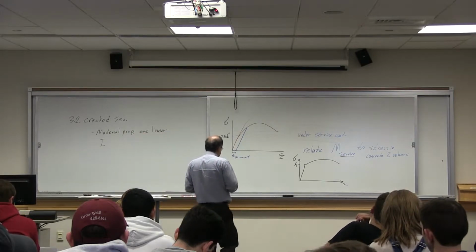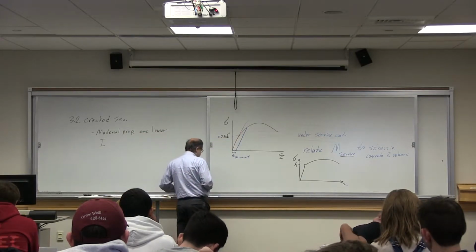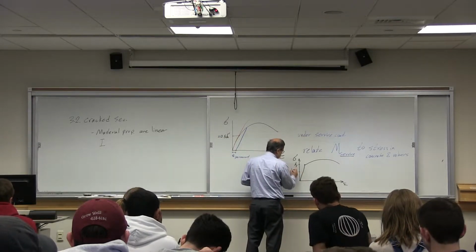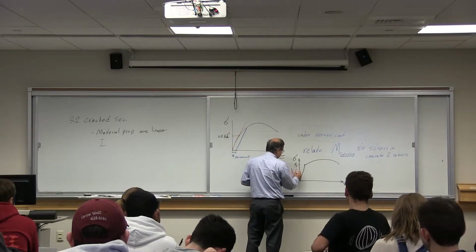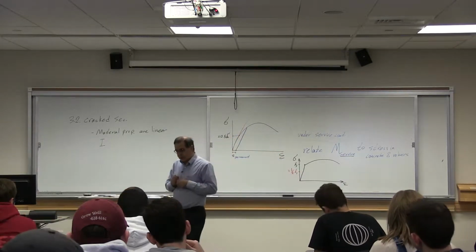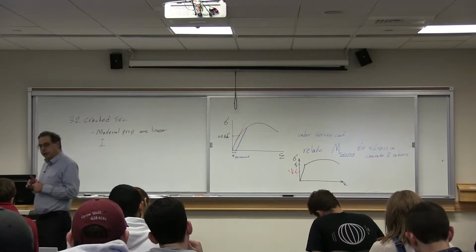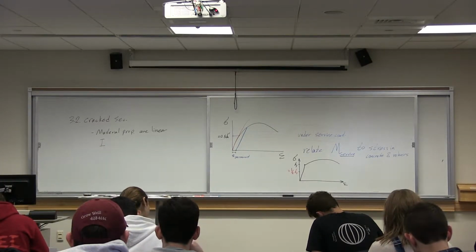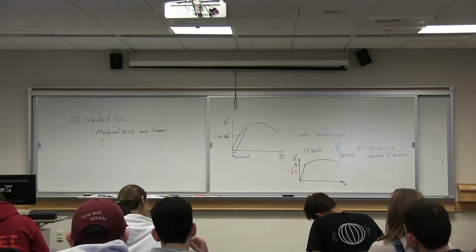Again, based on past experiences and experiments, approximately, if you limit the stress in the rebars to 1/2 of Fy, you would be able to control the crack size to a reasonable opening.